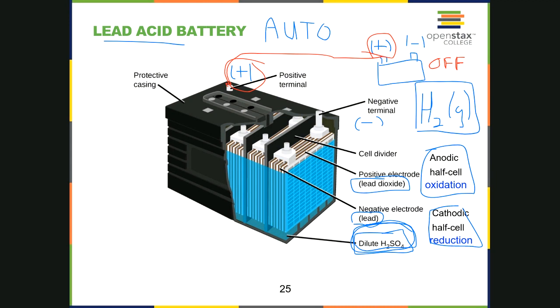Then the next thing you're going to want to do is go from the donor battery's negative terminal, but not to the negative terminal on your car. You want to attach it to what is called a grounding point. So this symbol is representing that.